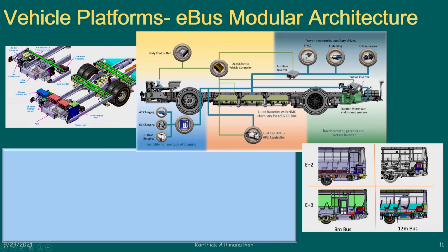And then you have the big daddy, the traction inverter and the traction motor, right. That is the one which is going to decide the level of performance. And having gotten the traction motor, depending on application, the weight, the motor's torque and the vehicle's torque requirement or GVW, you might have to gear it, and you might have to put in a transmission, predominantly automatic transmission. And you've got your lithium batteries here, either NMC or LFP, it depends a lot on what the financials are, and you might have a fuel cell controller and a fuel cell to keep pumping energy into the battery, right.